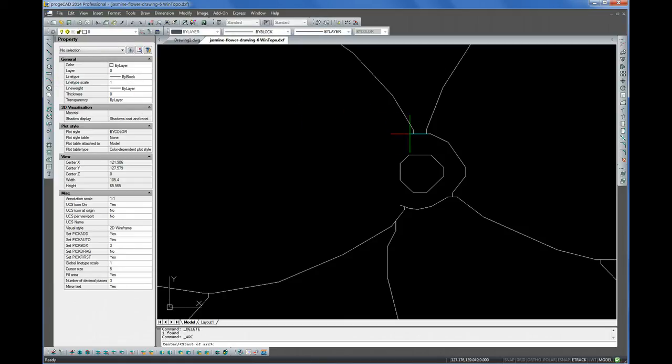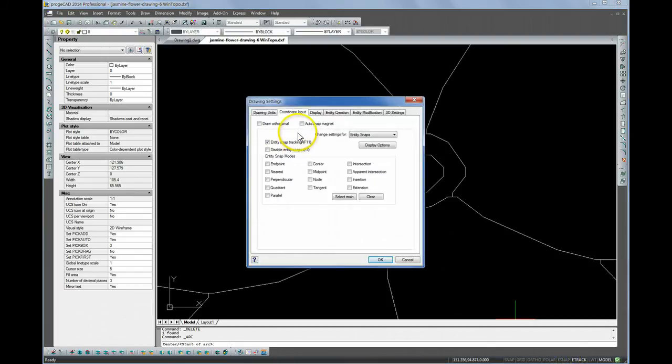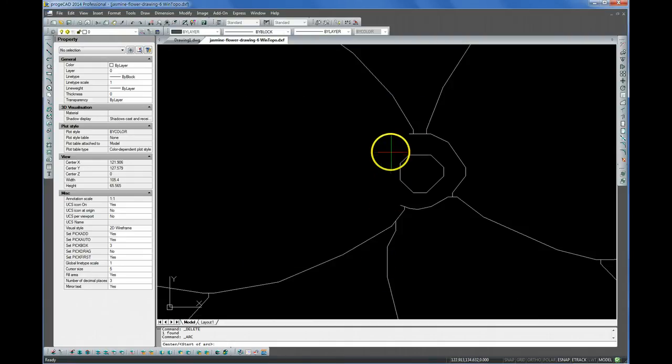Okay, now you remember in SolidWorks it would often grab onto a point. And the reason it's not doing that is I don't have one setting. Down here you see Entity Snap, eSnap. Make that white. And then it brings up an eSnap control box. I would suggest clicking Endpoint, Center, Midpoint, and Intersection. Say OK. And now when I hover the mouse near that point, it grabs it. That's very nice. So I'm still in this arc toolbox.